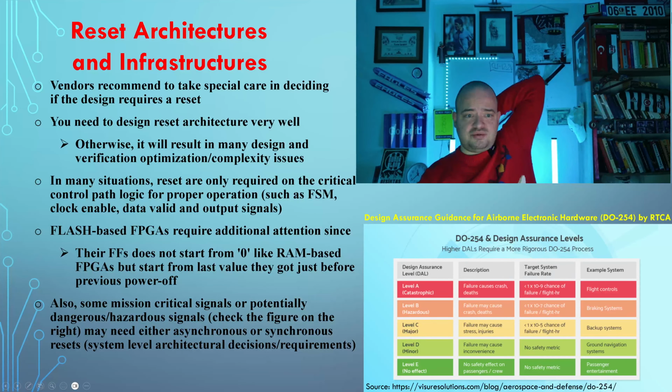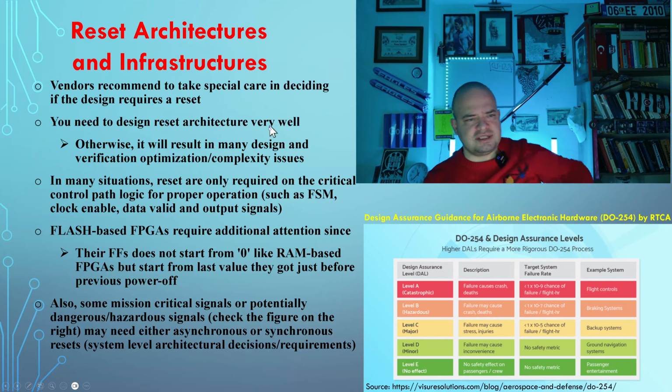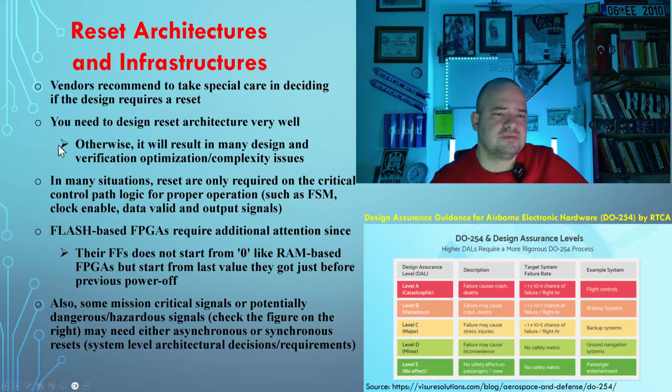Okay, so we provided some details regarding reset architectures and infrastructures. Let me read each bullet. Vendors recommend taking special care in deciding if the design requires a reset. You need to design the reset architecture very well, otherwise it will result in many design, verification, optimization, and or complexity issues. In many situations, resets are only required on the critical control path logic for proper operation, such as finite state machine signals, clock enabled, data valid, and critical output signals.